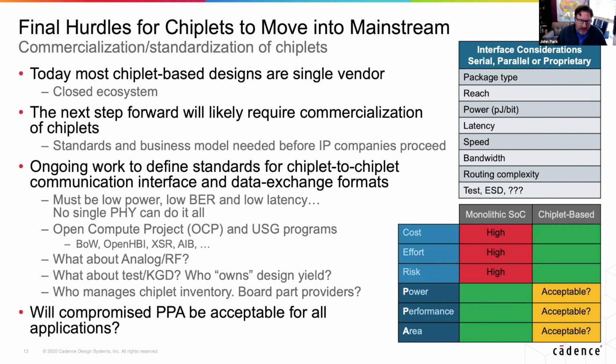In my opinion, there's going to be no way you can come up with a single communication protocol for all chiplets. In my view, it'll be like a PCB world, where I have memory standards like DDR4, and serial interface standards like PCIe. So there will be a grouping of standards that are developed that work across different packaging types: high cost, low cost, different bandwidth, all those types of things. That's my opinion of where it's going.